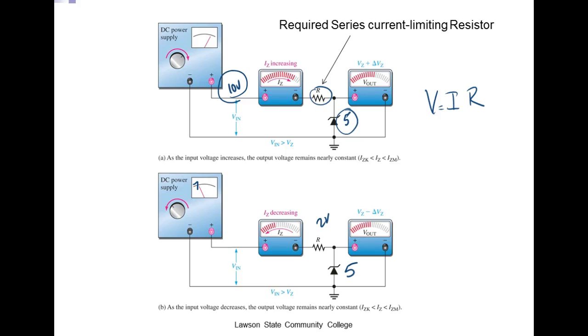So what has to be changing in the circuit? I didn't change the size of this resistor. Let's say this is a 1K resistor. To drop 5 volts, it's got to conduct 5 milliamps. But it's 1K, and it's not changing, right? Down here it's still 1K, and now it's going to conduct 2 milliamps.